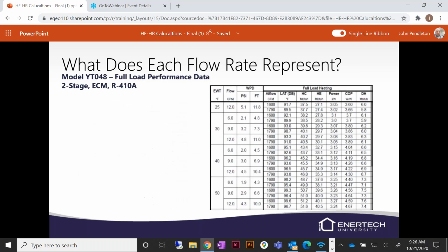Sometimes when we get into the variable speed flow centers with the controller on it, it will use the exact specific gravity. So if you look at the screen on it and you do a hand calculation of your heat of extraction, those two numbers could be a little bit off from each other. That's because the computer in that control module will use the exact capacity factor of that antifreeze type.